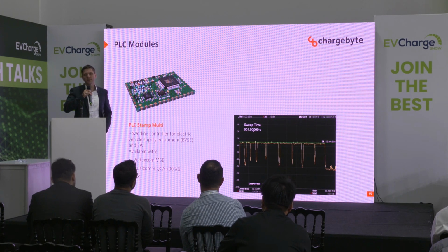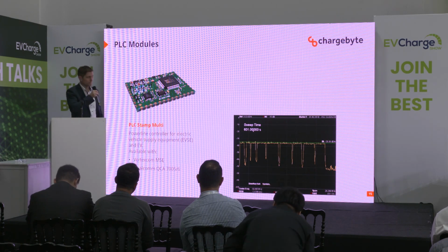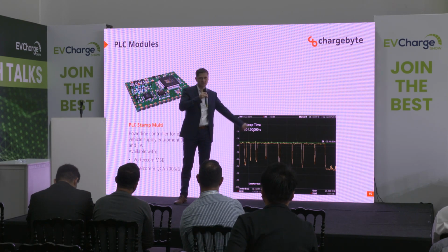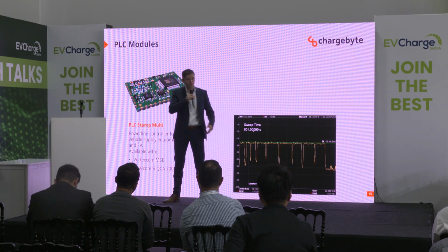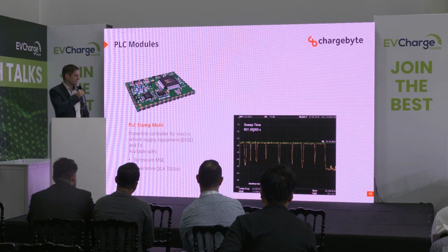On the other side, you have then a high frequency power line signal. And we're taking care that this is flashed, that it's calibrated, that the spectrum mask is not overshooting, that you have a smooth and flat spectrum mask, and no noise on that. And if you have that, then you can communicate over power line, okay?